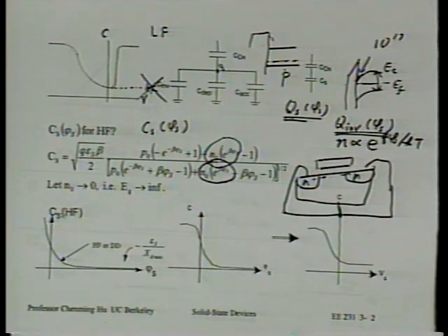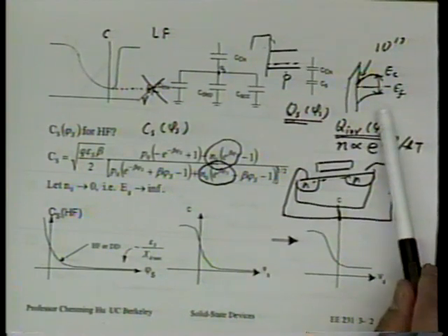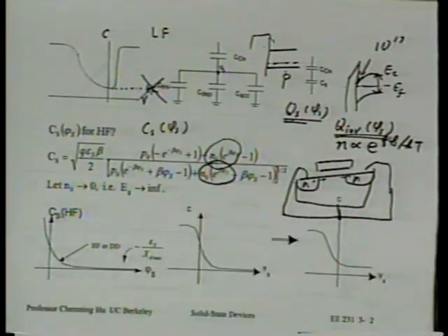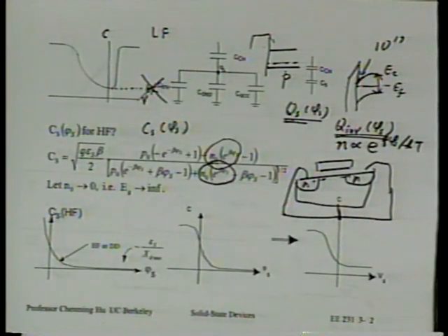But today, if you want to get a capacitor, you have to go to a wafer that contains a lot of transistors anyway. So there's no need to avoid using transistors. The standard structure for us to measure the CV curve is a transistor, not a capacitor. And therefore, we can get the low frequency CV curve all the time. That's another reason why this name, low frequency, could be a source of confusion. I don't like that name, low frequency.